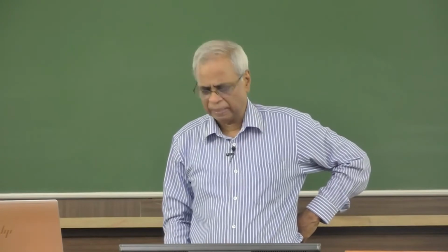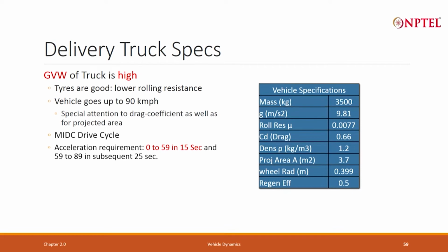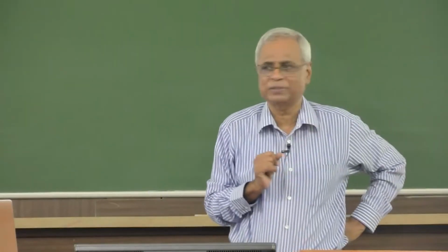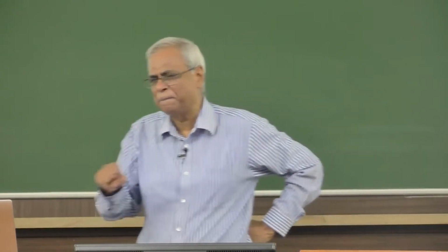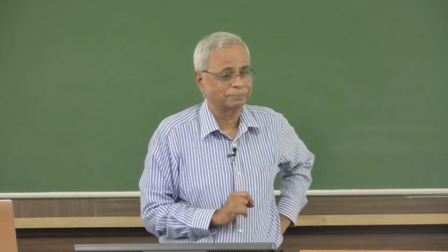So, something that you have seen between 59 to 89 seconds it travels. There is an acceleration requirement. This is something that we had not taken, but the acceleration requirement is in the first 15 seconds it should be able to go to 60 km per hour. You will see that this does not impact the power or energy as much, it will impact the torque.